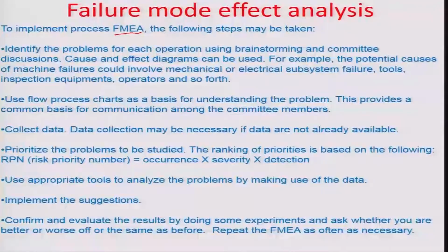One is to identify the problems for each operation, and this can be done using brainstorming or committee discussions, and then try to plot cause and effect diagrams, which will give you an idea of what the reasons are in terms of man, material, machine and methods, which all together give you the onset of a problem or a failure mode. And once this organized fishbone diagram is